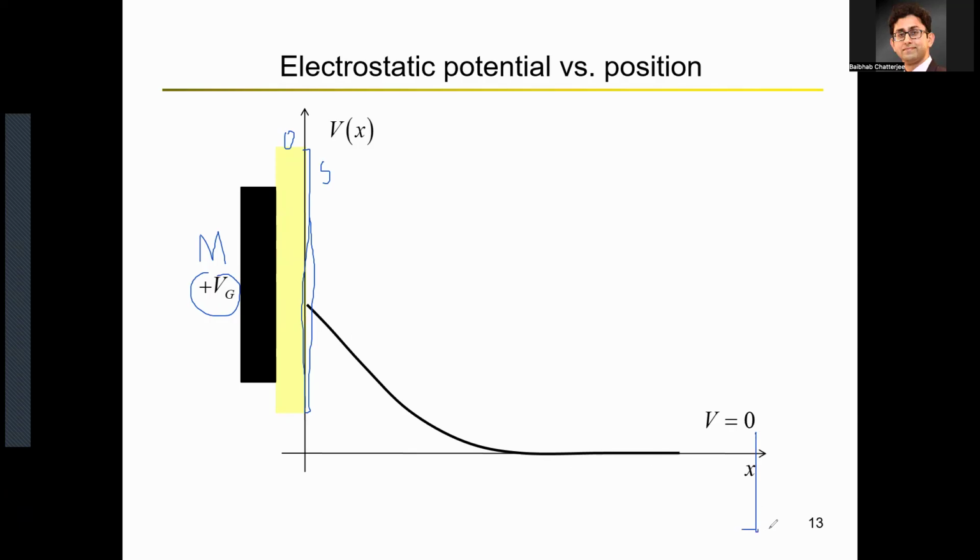This side is connected to ground, but the semiconductor is not a perfect conductor. If it had been a perfect conductor, with infinite conductivity, then as soon as you connect ground to one part of it, everything would be connected to ground. But because it is not a perfect conductor, everything will not be connected to ground.